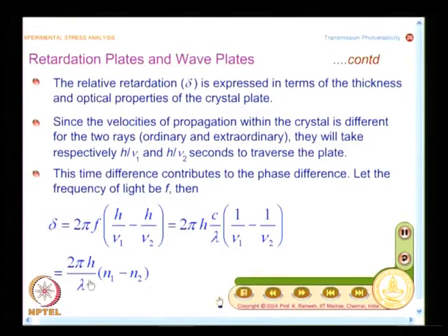It is very important. See, I said that for the mathematical development of photoelastic analysis, the mathematics becomes a lot simpler if I confine our attention to a monochromatic light source. Where does this come in? Till now we wanted to see colors, so we used white light, we enjoyed seeing those bright colors. But when I come to mathematical analysis, we find a crystal plate behaves like a quarter wave plate for a given wavelength. The same is applicable for wave plates as well as the model behavior.